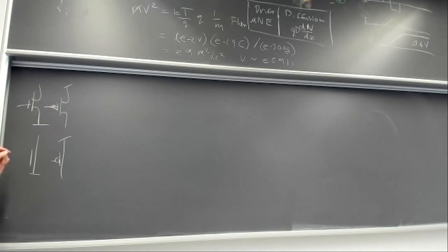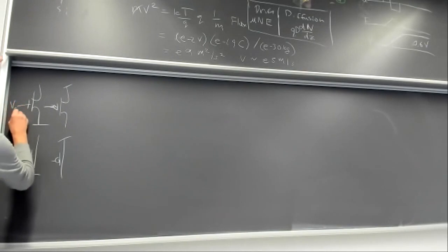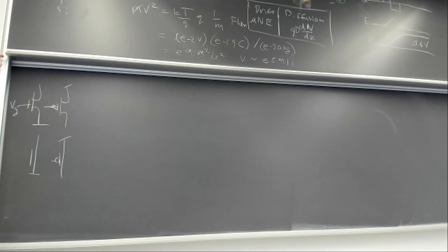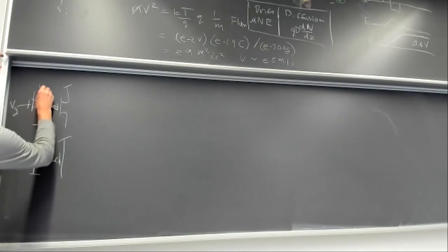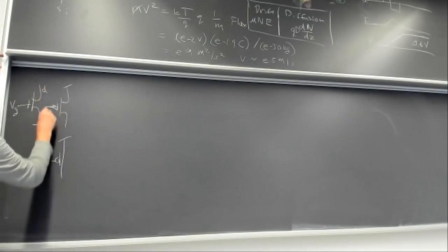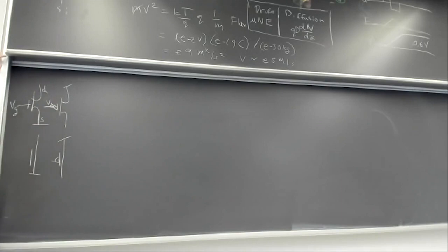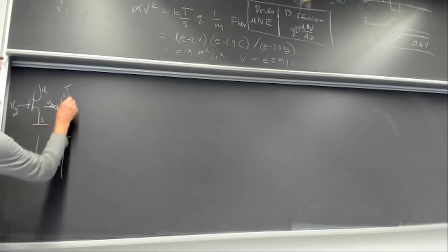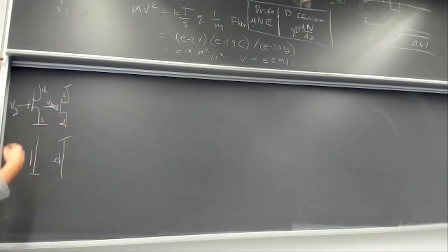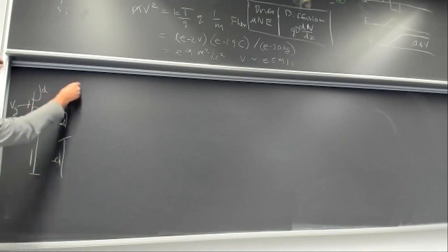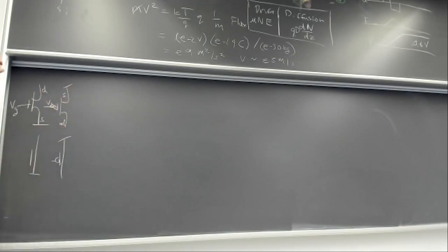It's clear, right? That's a symbol for this cross-section thing up there, where this is the gate. Where do the electrons come from? The bottom, right? So this is the source, and they fall out of the drain. And now for the PFET, this is the gate. Where do the holes come from? This is simpler, right? Holes go from high voltage to low voltage, because they're positive charge. So it's really easy. The source is always the higher voltage. They fall from high voltage to low voltage in the direction of the electric field.